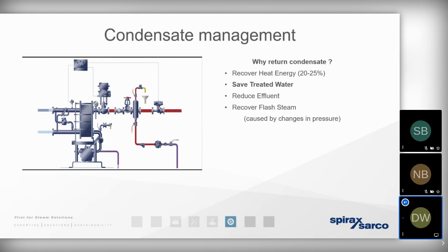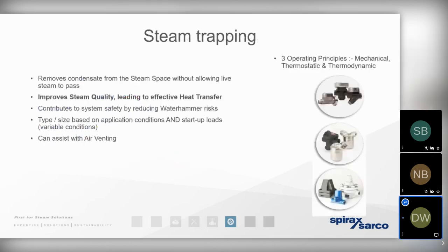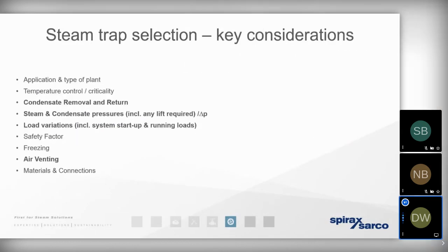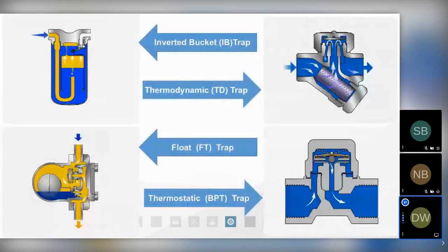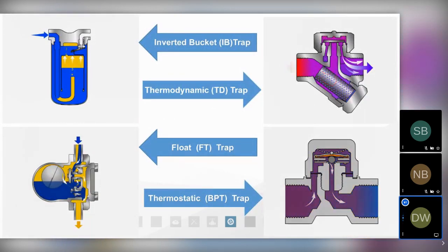So that means that in order to allow the condensate to move away from the network, we need to ensure that we've sized and selected the correct type of steam trap, which you remember we went through in some considerable detail a few months ago. We looked at how there's no such thing as a universal steam trap, and we need to ensure that we're getting the condensate away from the process at the correct rate.